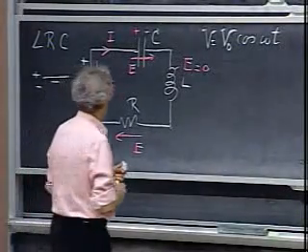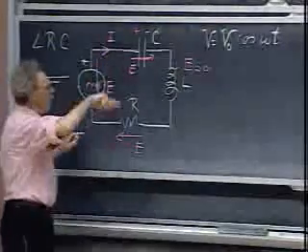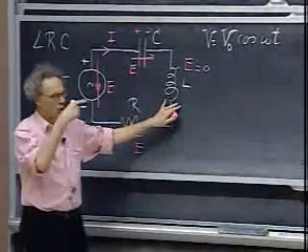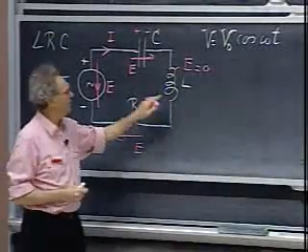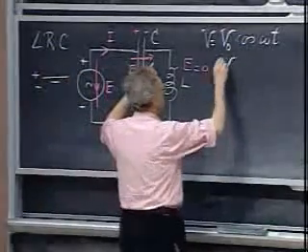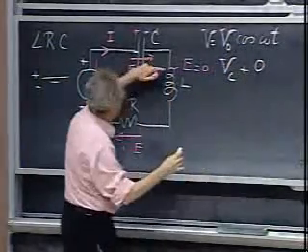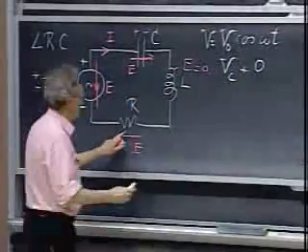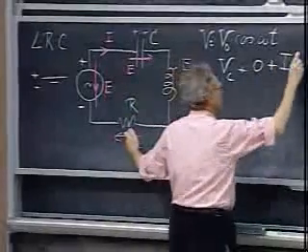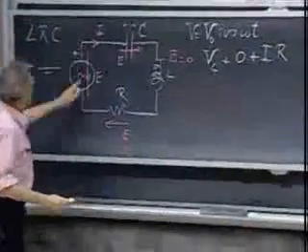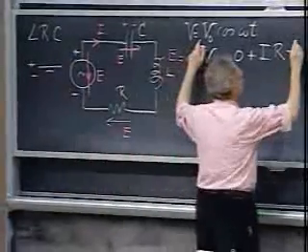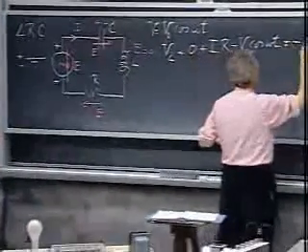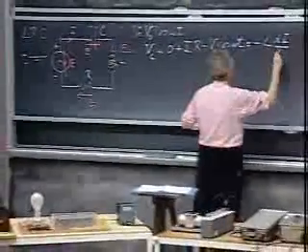So if I set up the differential equation, I start here. I always go in the same direction as I, because only then is the closed loop integral minus L dI/dt. So I go over this capacitor, that is V of C. Then I go through the wire of the self-inductor. There is no electric field, so the integral E dot dl there is zero. Then I go through the resistor, so I get IR. Then I have my power supply, so I get minus V0 cosine omega t, and that now, according to Faraday's law, equals minus L dI/dt.